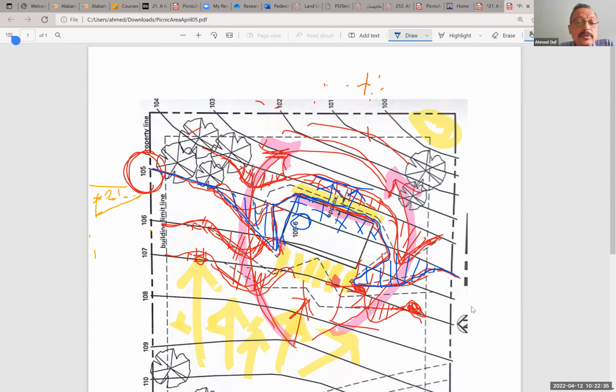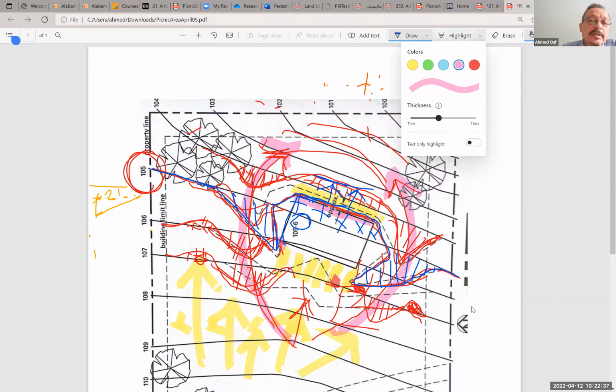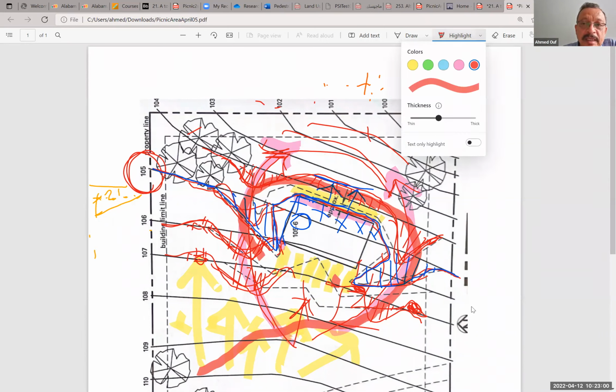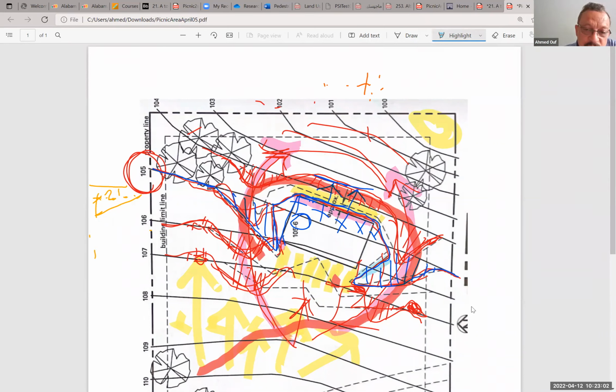Last time we were working on only the pedestrian path, like we can move it like that to have a slope of 1 to 20, and then we enter the site from this area, and then we go back like that. But when I'm having to move earth and do the pedestrian path at the same time, I have to make sure that a swale like that doesn't coincide with my pedestrian path.